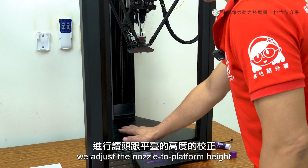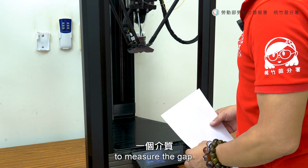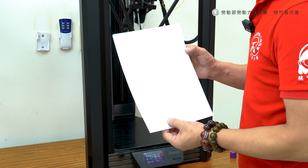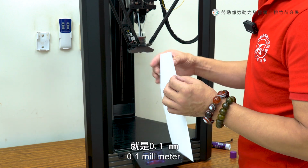Next, we adjust the nozzle to platform height using a sheet of A4 paper to measure the gap. This A4 paper thickness we've measured is 10 lines, which means 0.1 millimeter.